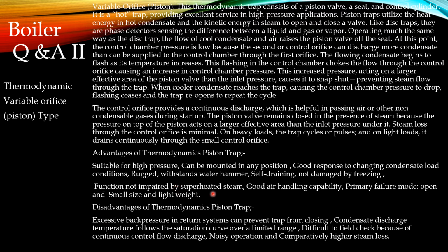Function is not impaired by superheated steam, so you can use it for superheated steam. Good air handling capability, so it can be used at initial startup. The primary failure mode is open; when the trap has failed, you can hear a louder noise as the trap will be in the open condition, so you have to take it for repair. And it is small in size and lightweight.